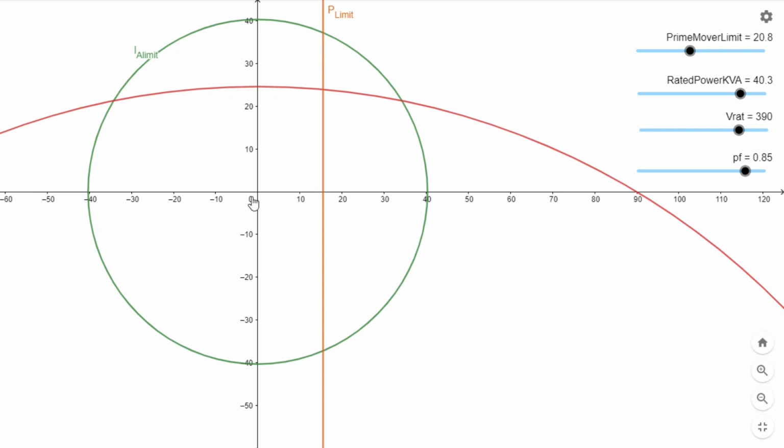So once again, the x-axis represents the real power and the y-axis represents the Q power. Notice that we have rotated it on its side and reflected it so that on the right-hand side, we are generating real power. On the left-hand side, we are consuming it. So in the real sense, your generator would only operate on this area in the right-hand side.